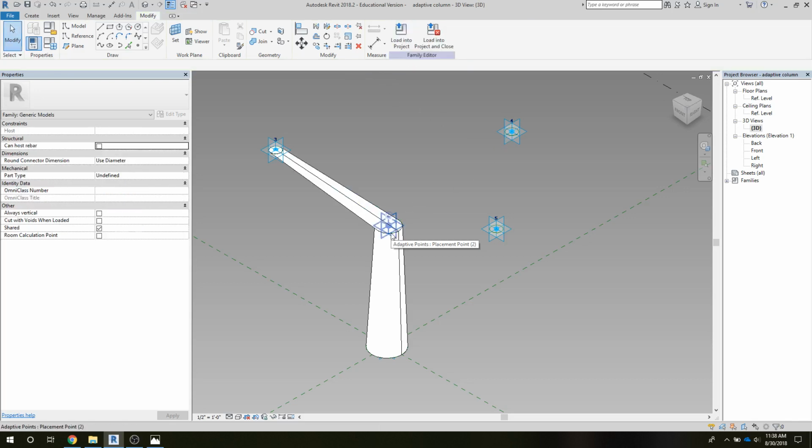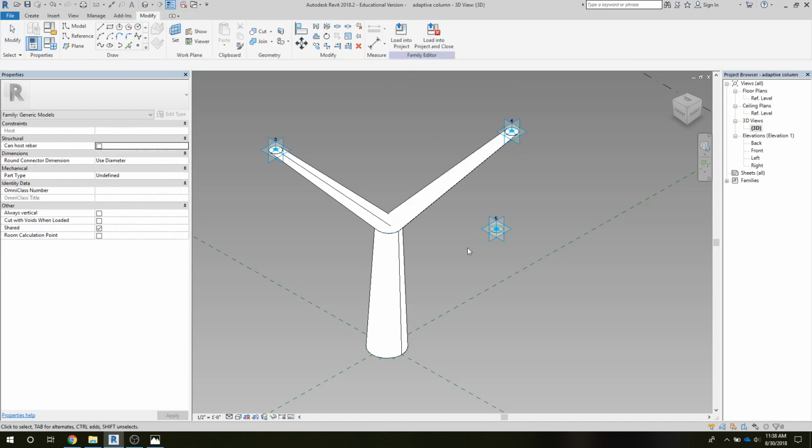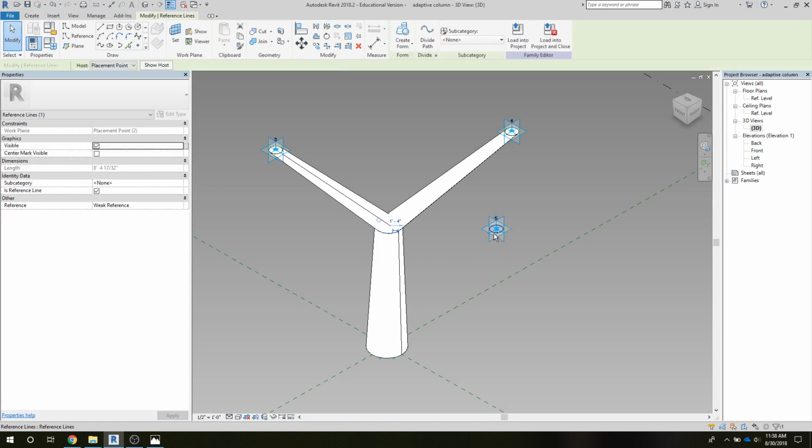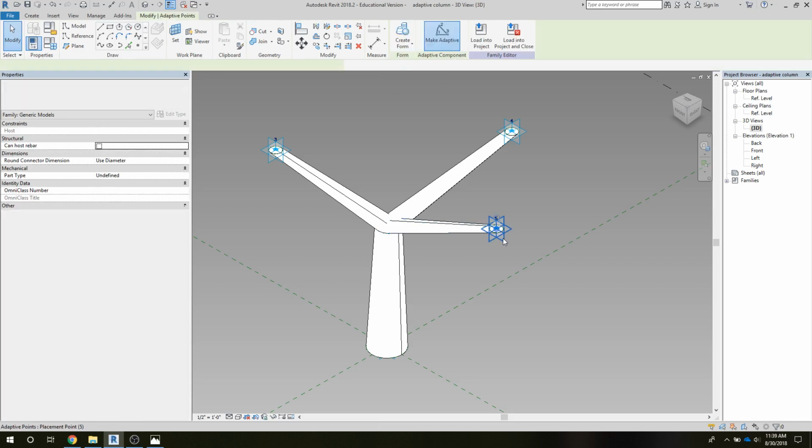And then we'll try to grab that circle again, tabbing around, and grab the other one, solid form, and once again grab, and oops, I thought I had it. It may just disappear, so let's just come over here and grab those. Got my two reference lines and create form. And we can check out to see that we have adaptive behavior.